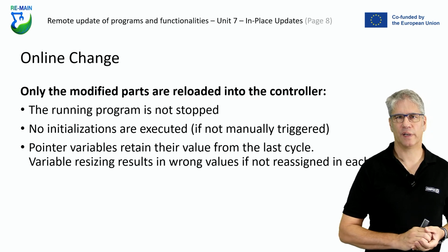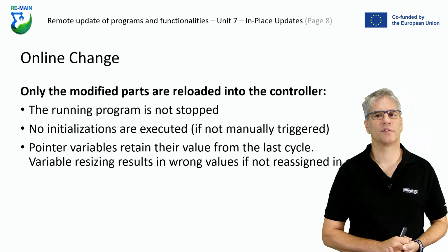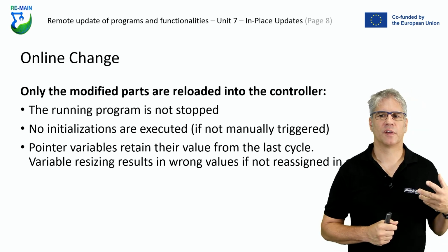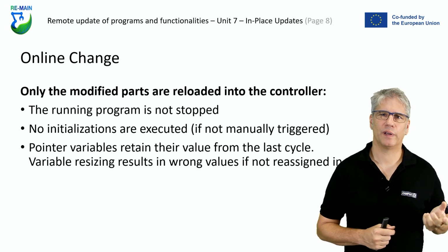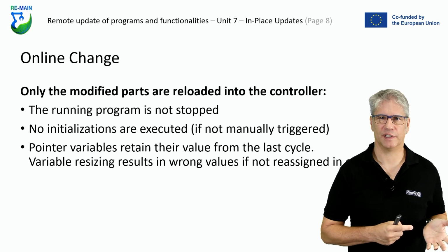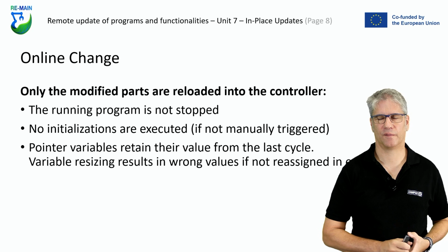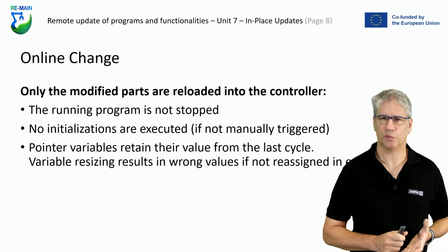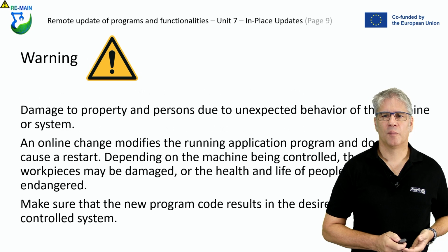And be aware that if you're using pointers, something that I personally would not suggest, pointer variables retain their value from the last cycle. And if they point to other variables and their size could have changed, then the result of the pointer's functionality could be totally wrong, leading to a malfunction of the machine. And this is pretty dangerous.